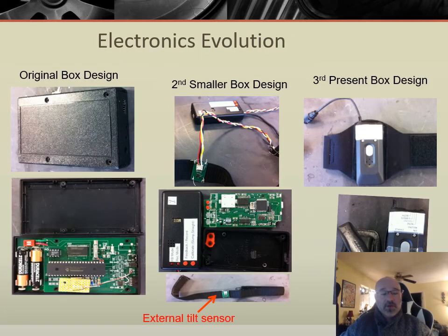So we talked a little bit about our control systems and how if a system wasn't stable, we'd need to go back and make revisions to the electronics, the components, the portions of the system in order to make sure that it is stable. And that's what we're talking about here for this project, our electronics evolution. So if the system wasn't stable, we had the issues with the common grounding, the shielding, the noise, the disturbances, all of those types of things would cause us to go back and do some development.